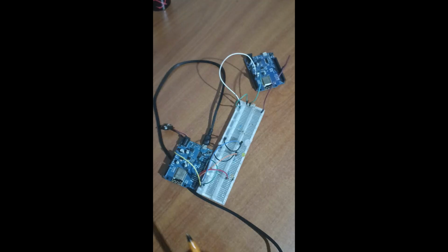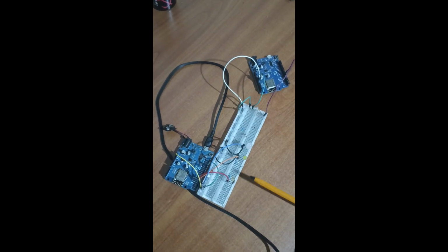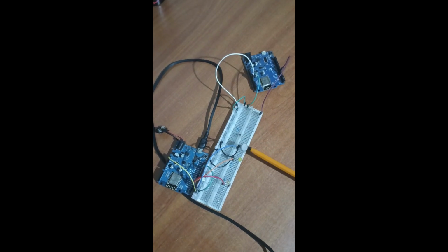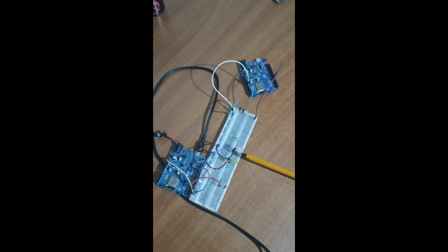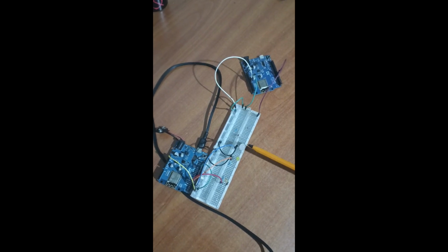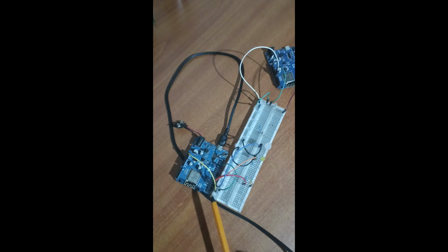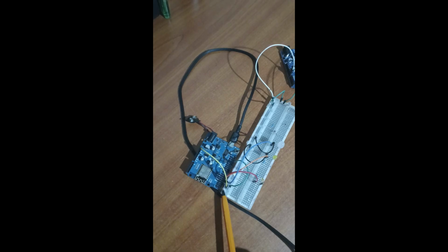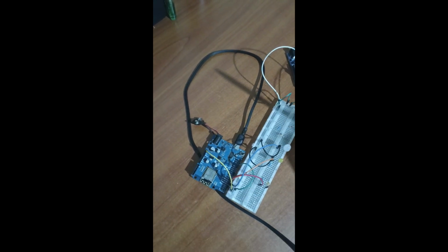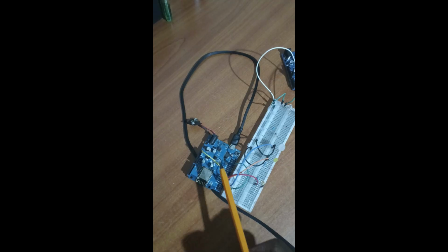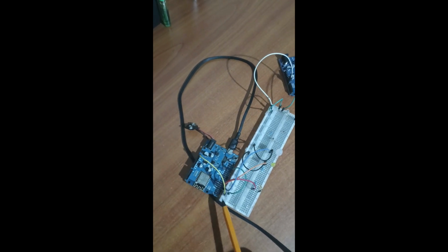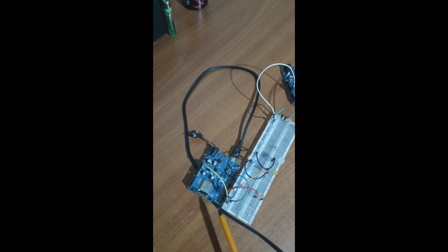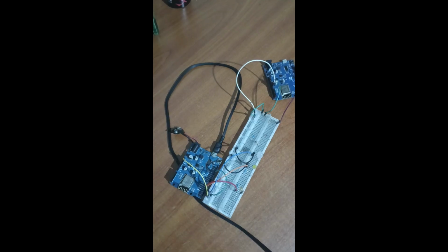For this setup, this is where you are connecting 3 different LEDs. So this is a red one, this is a yellow one, and this is an RGB, red, green, blue. But at the moment, I'm going to use the color green alone. So as you can see, I've connected it. This is a breadboard. Here we have a negative line and the positive. They run this way. So if you connect 5 volts to this line, everything connected to this line will pick 5 volts, but this one is powering the other microcontroller.